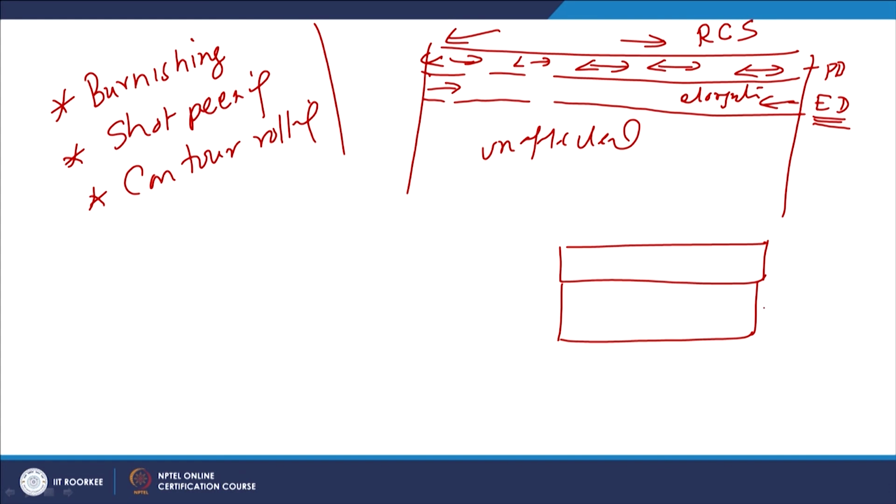So, this is what we can see: the subsurface zone, which is under elastic deformation, is trying to come back, while the surface layers under plastic deformation experience the tensile strain. Because of these two opposite effects, surfaces experience residual compressive stresses, while the subsurface zone, which is not allowed to return, experiences tensile residual stresses. Tensile residual stresses in the subsurface zone are not as harmful as compared to the surface layers.